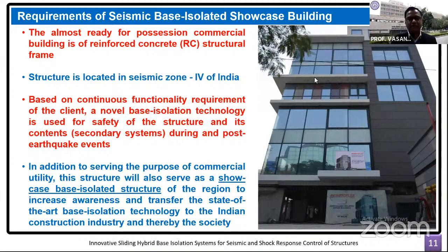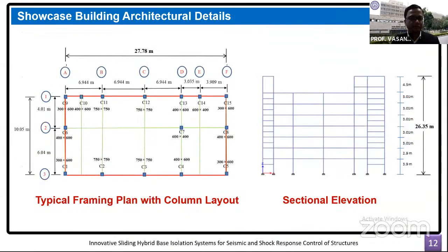I'm making this kind of disclaimer that it is not always hard and fast that you put the isolators one story above. It is again a decision of the designer as to at what level the isolation systems are to be put. In this particular project, the decision related to the placement of the isolator was based on this requirement of exhibiting the technology to the visitors.